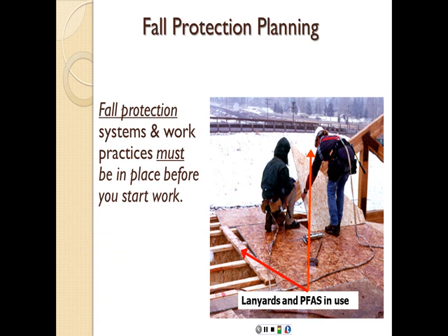For fall protection planning, fall protection systems and work practices must be in place before you start work. So we're not gonna start worrying about fall protection after we have already started. You have to plan it in advance. Where are you going to provide your anchor points, for example, in case we use the PFAS? Where are you going to locate your safety net and how far from the edge, and so on and so forth? We're going to talk about some specifications and some details in this lecture.